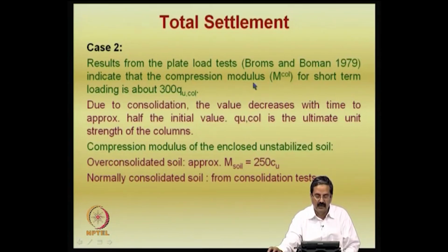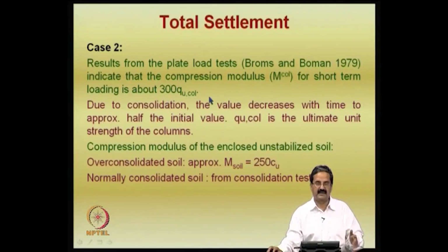The model they are trying to relate modulus. How do you get modulus? You will get it from plate load tests. Like I said, you also have in the literature, if you want to get the E value, E is 10 times Qu or some sort of equations, we have seen that. We have some more equations in the literature where, if you know the strength properties, you can relate it to stiffness.